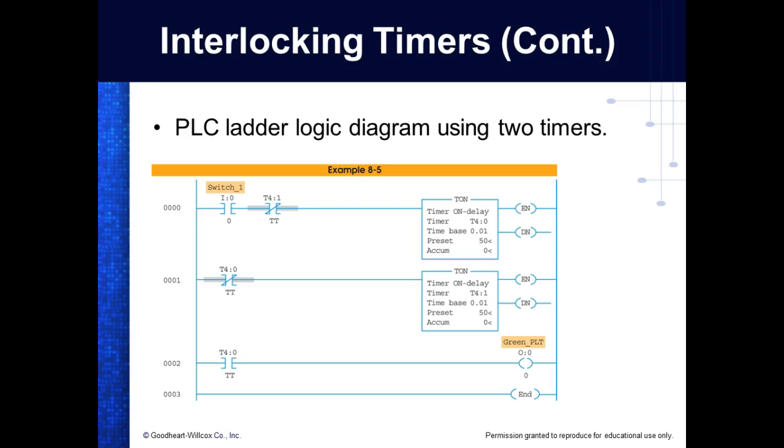So this is normally closed on timer 1, and then timer 1's got timer 0 normally closed. So when I close my switch, timer 1's going to start timing, right? This guy's not going to start timing, but you'll soon understand. But when it times out, it's going to come up here and do what? Flip this over, and it's going to flip that over and flip that over.